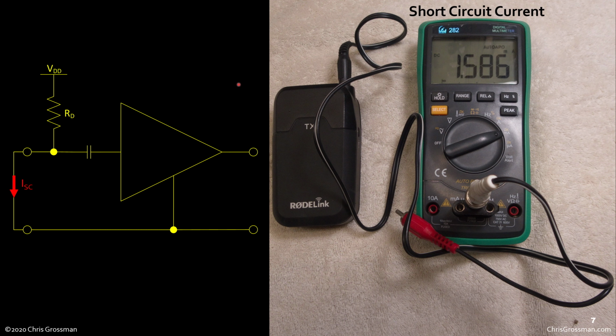Now we also want to know what this RD is, but we can measure the short circuit current. So we flip over and plug into the current input of our multimeter and switch it to the milliamp scale, and we measure the current we get. Of course I'm ignoring the input resistance of the meter, but this is close enough.